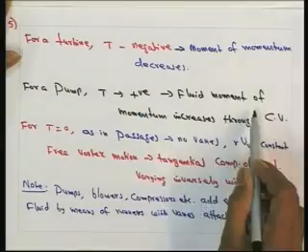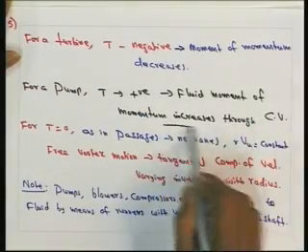Instead of the turbine extracting power from the fluid, the pump is imparting power, that is momentum, to the fluid which it is pumping. So, for a pump, T will be positive, so fluid momentum increases through the control volume.